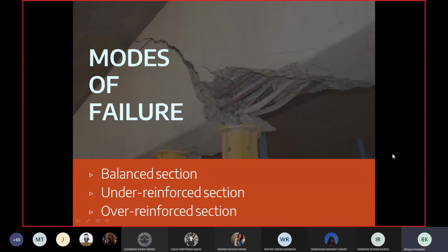And that is the reason why it is very important to provide a sufficient amount of cover. When that is followed, the possibility of concrete falling off the surface and exposing the steel is minimal. This happens only when there is no adequate cover.